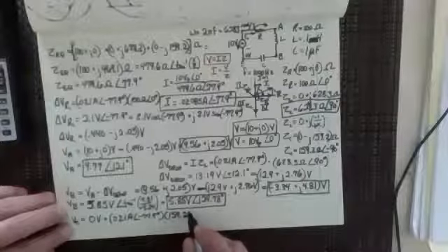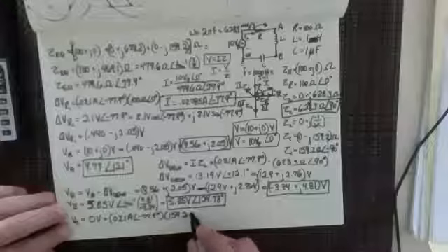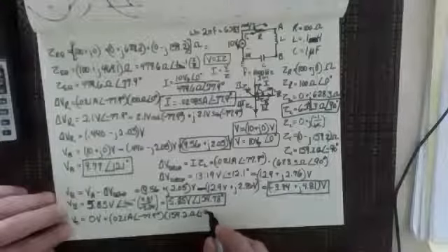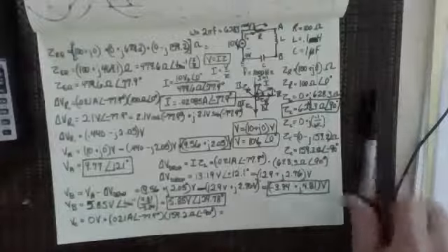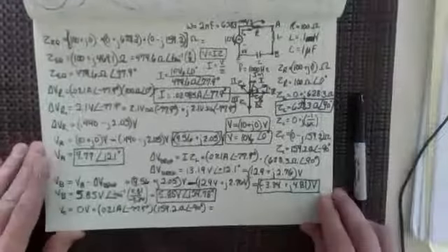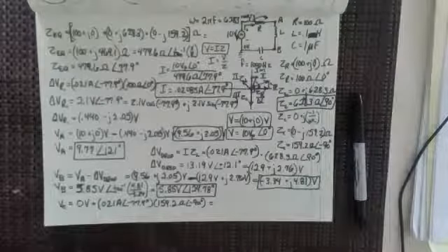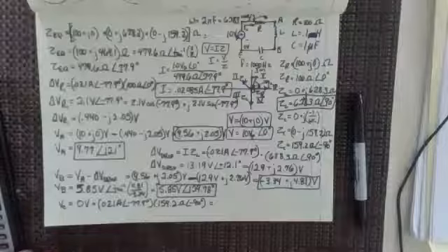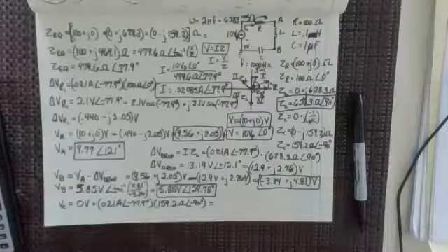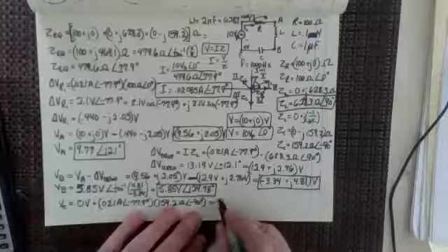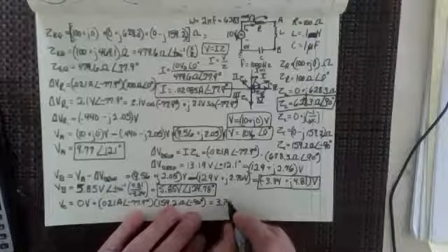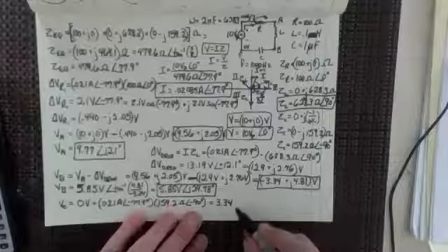And then we want to add in the impedance of the capacitor, which is 159.2 ohms at minus 90 degrees. So when we multiply those two things together, I hope I've still got that all on there. Oh, yeah. So when we multiply those two things together, 0.021 times 159.2, we end up getting 3.34, right? 3.34.